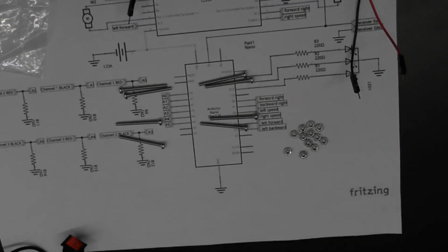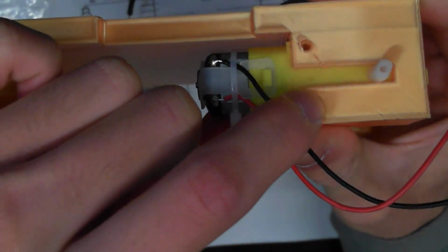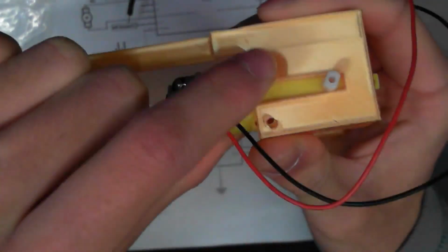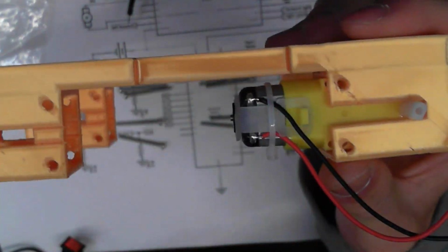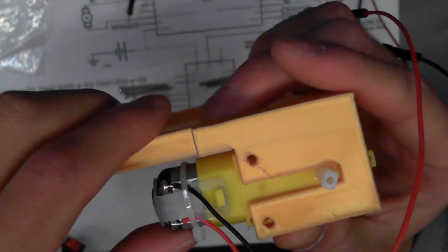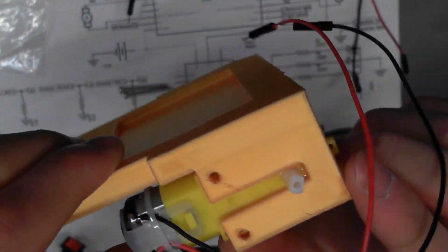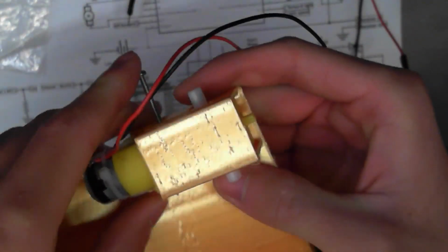Okay, small problem. I think the clearance on these is not as forgiving as we had thought. It seems the only one of them seems to line up well. The other one, is your guys' like that too? Okay. In that case, we'll just be mounting one bolt per motor, which should be okay. It's on this side, so this part might fly off, but that should be okay, I think. So if that lines up, just send a bolt through there, and it should come out the other side, just like that.